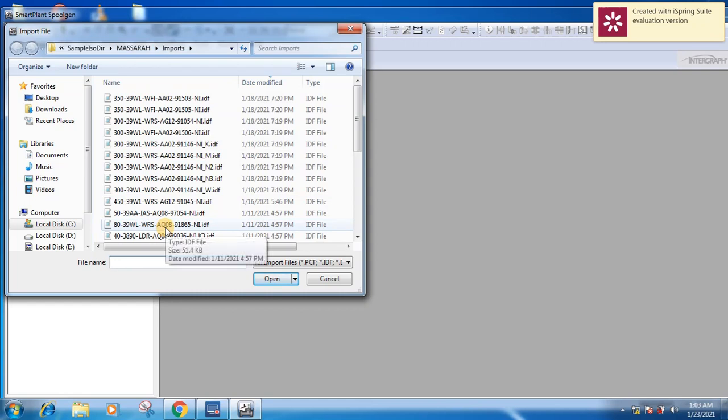Now project creation itself is an admin part, and it's a separate task. Generally, the admin decides each and every setting of a particular project, which includes whether the diameter is in inches or in mm, what exactly the north of the plant would be, and what the weld tolerance and weld gap will be.